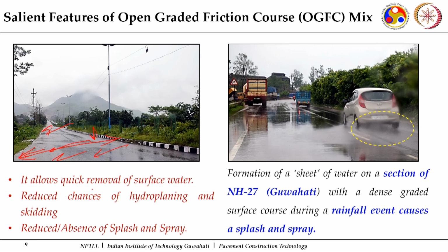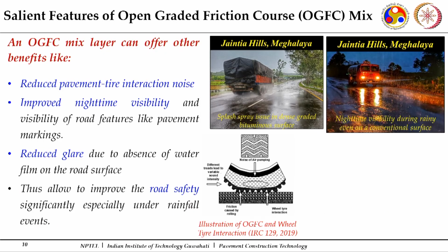So, the benefit is it quickly removes the surface water and reduces the chances of hydroplaning and skidding, because if you apply a brake when a water film is there on the surface, chances of skidding are very high. And splash and spray, because if you are traveling behind any such vehicle, splash is there, your visibility gets reduced, and this becomes more challenging, especially when you are driving during night times.